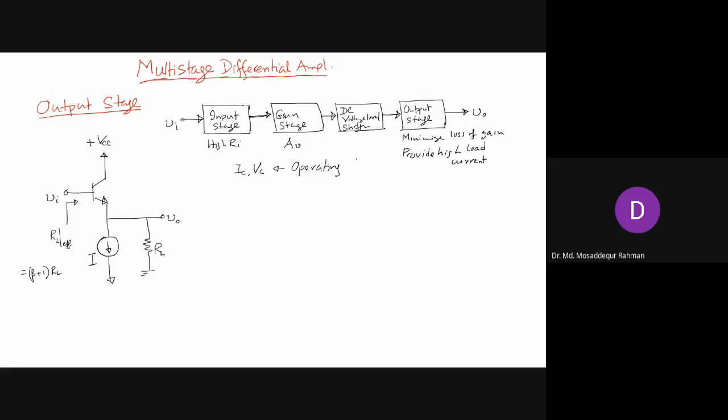So you need to ensure that, and we have discussed in detail how to check whether the bias voltages can support your signal voltages. For the whole range of signal voltage, the base-emitter junction will of course remain forward biased. In addition, the collector-base voltage remains reverse biased for the whole range of your signal voltage. That is how you ensure that your transistor is operating in active mode.